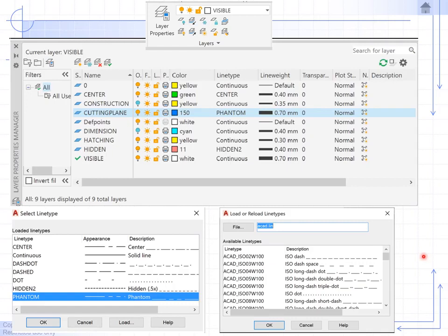So you're going to have to set up your own layers from scratch since you're starting the AutoCAD file from scratch for this chapter, sectioning in AutoCAD. Unless you use one of your old AutoCAD drawings that already have some of the layers set up, just open that file and save as with the new part number or file name. Okay, let's say you're setting up your own layers. So you go to the layers panel up in AutoCAD above, click on the layer properties, and you'll have the layer properties window pop up.